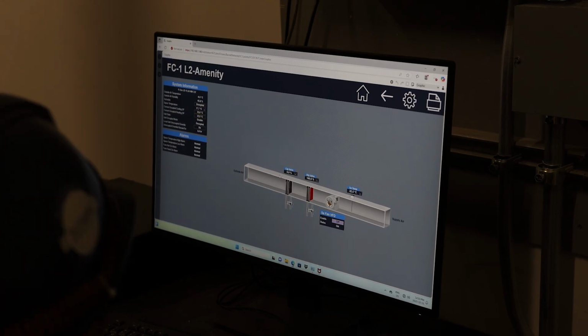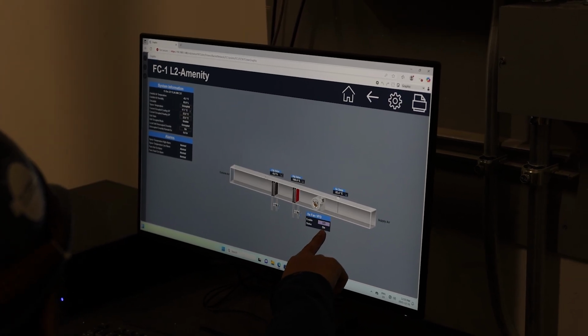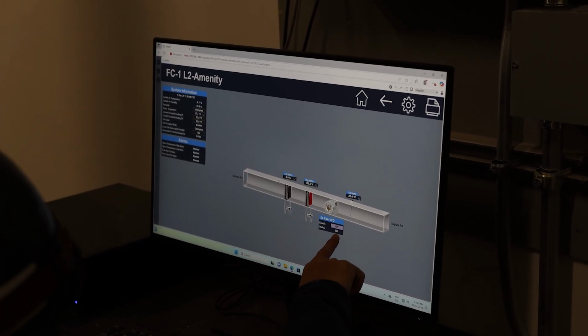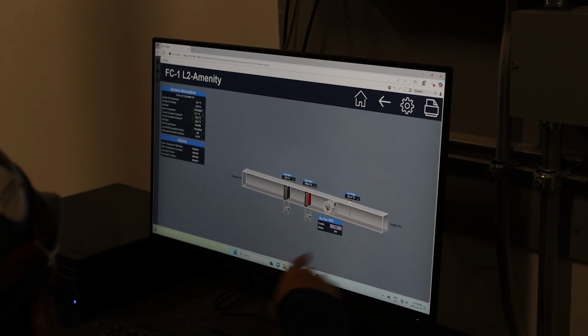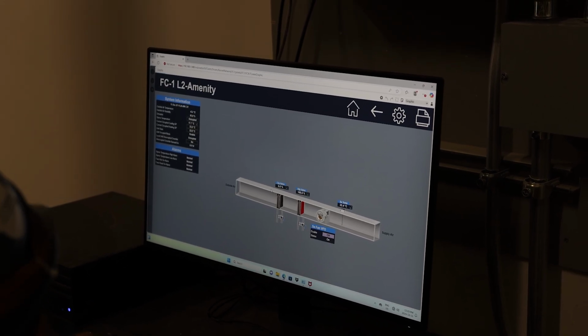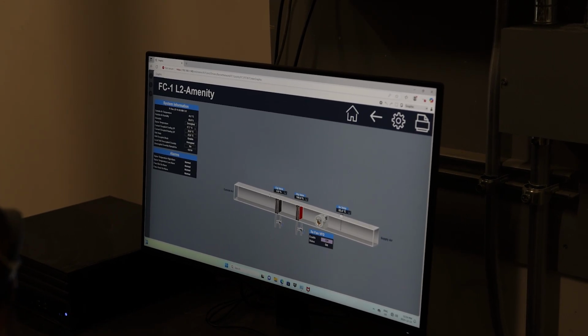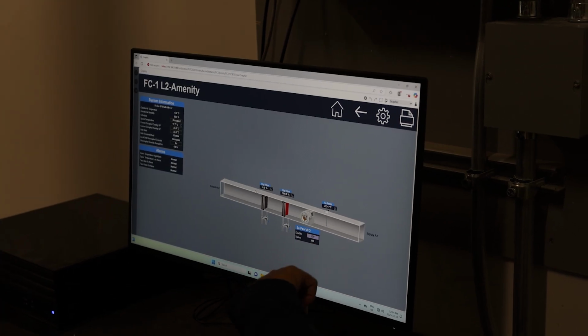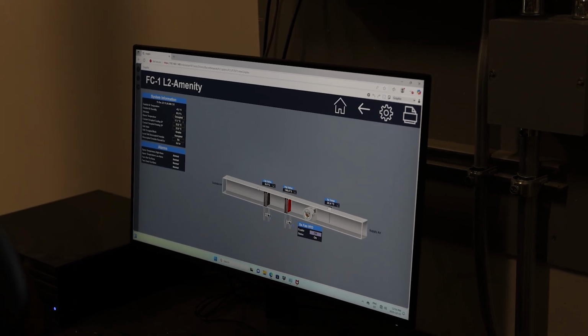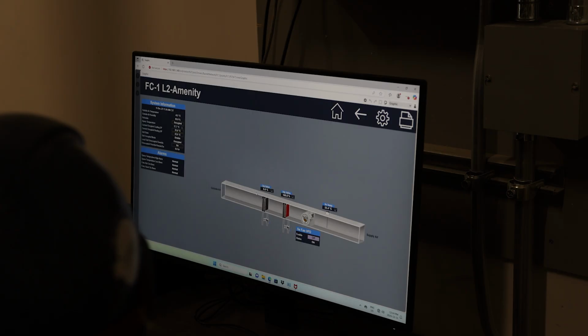So this is still on. We get this signal from the current sensing relay, CSR. As long as it's sensing the current, we will see the status is on. It takes a little bit of time because the fan is slowly ramping down, so we are still seeing the current.